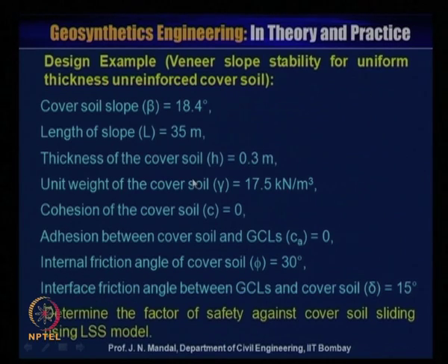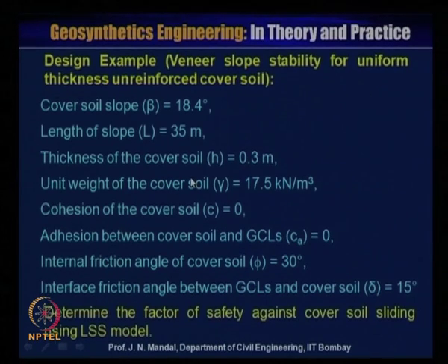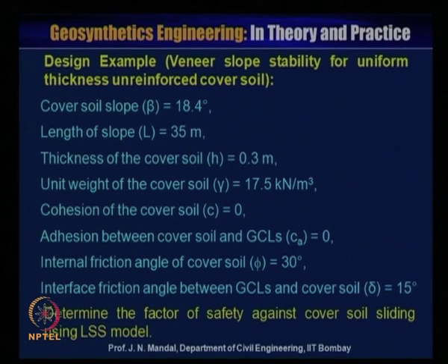So, once we know all these values, that is A, B and C, you can calculate what the factor of safety will be. Here I am giving one design example for landfill slope stability for uniform thickness unreinforced cover soil.